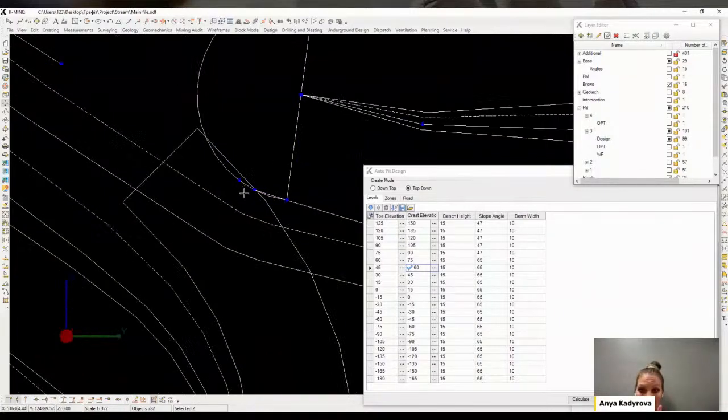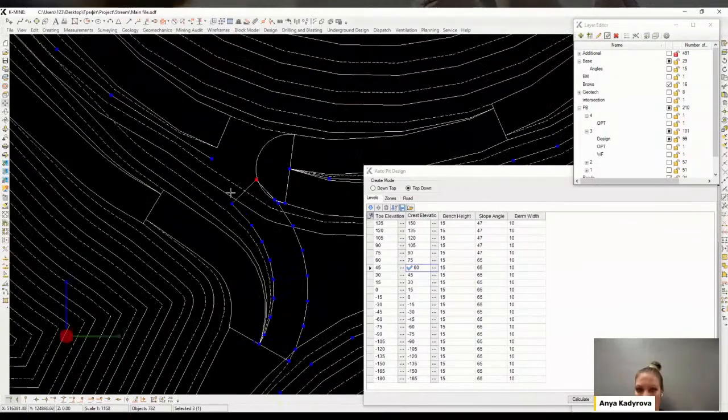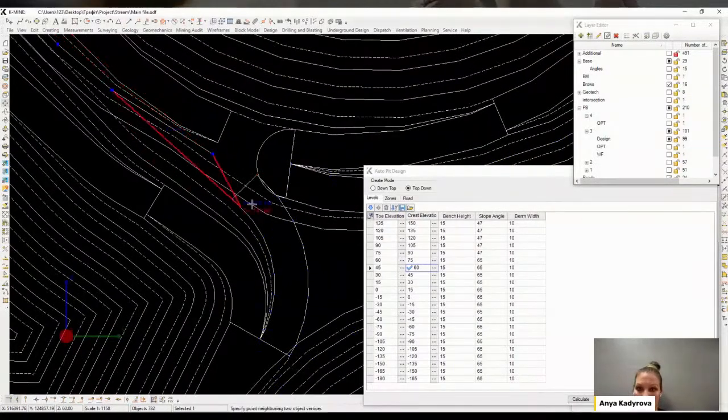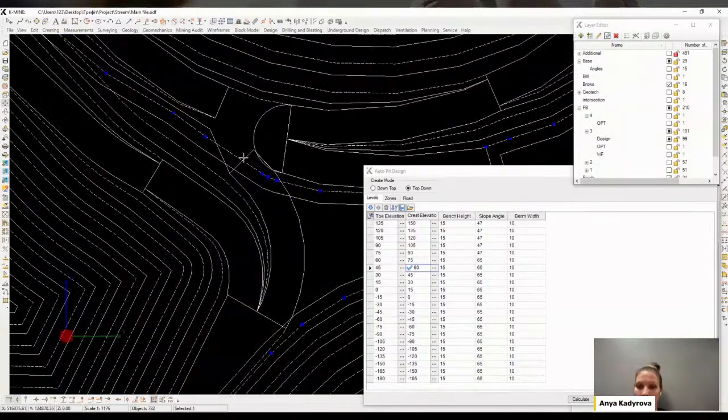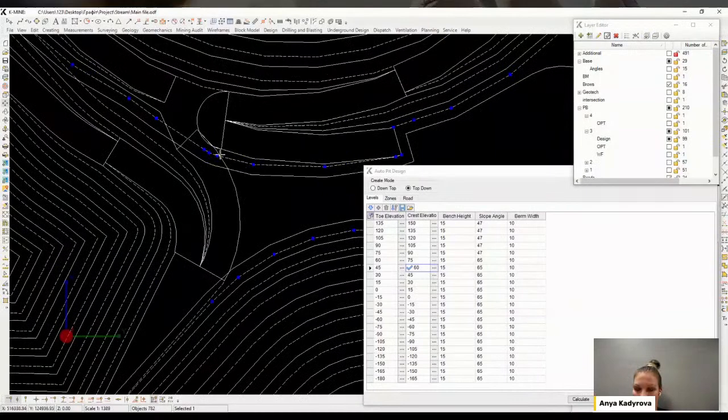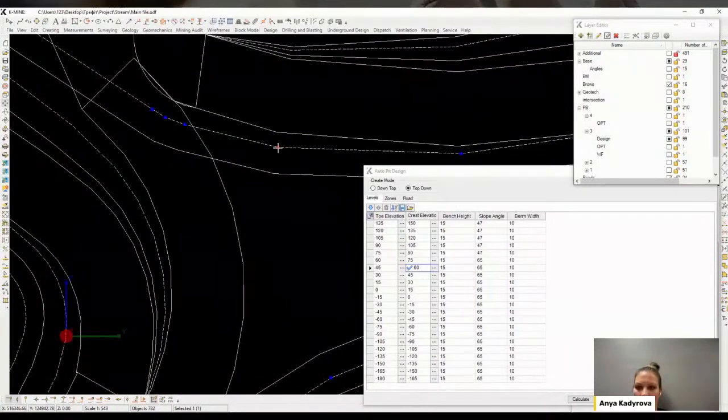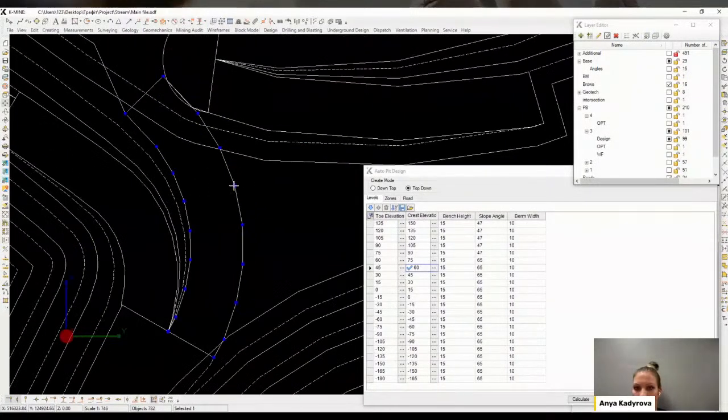Also, the design must be mineable in all cases and in all its areas. Roads also should smoothly transition from one pushback to another, providing a connection to the communication corridor. There are many more aspects to consider, but for our simple example, it will be sufficient.